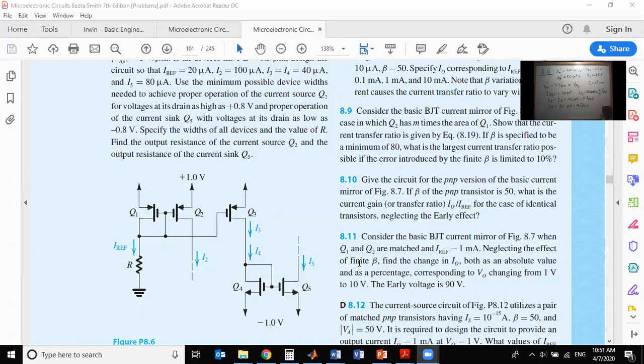Did that answer your question? I have a question. Sure. So for I5, it should also be equal to 2 times I4, right? Since it's in a current mirror with Q4? That's correct. That's definitely correct. So this is 2 times I4. Yes. And this is what we're going to use, okay? Because I5 is not directly connected to IREF. It's connected to IREF through I4, okay?